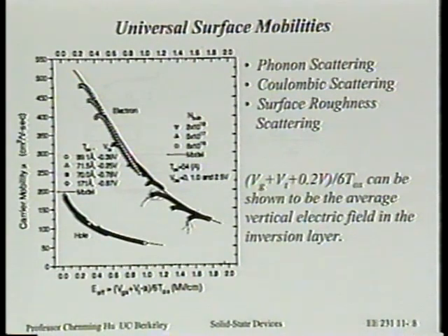I can tell you that whether surface channel MOSFET, or bulk so-called buried channel MOSFET, both are known to have order of magnitude larger 1/f noise compared to something like a so-called JFET. I don't know if you've ever had a chance with that.